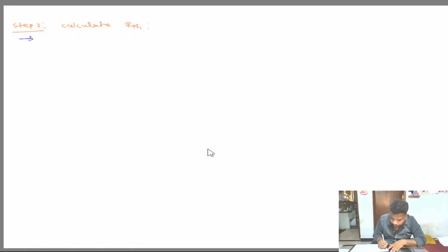In the given circuit, there are two voltage sources. The two voltage sources can be replaced by short circuit. Replace 120 volts and 65 volts by short circuit, and replace RL by open circuit.